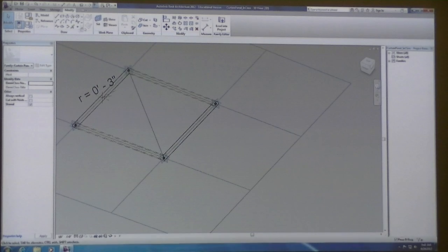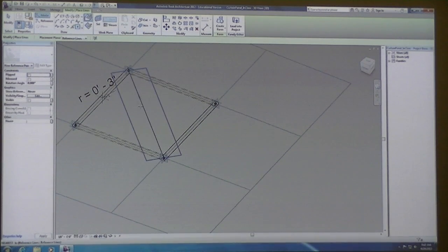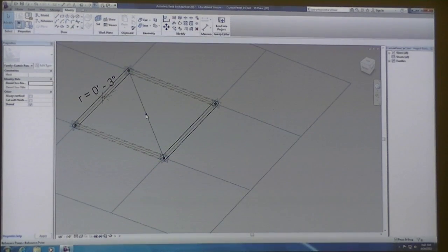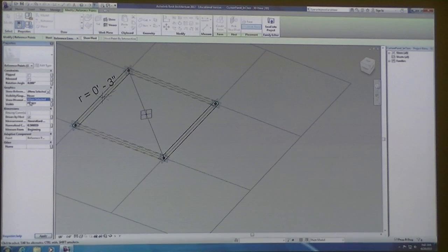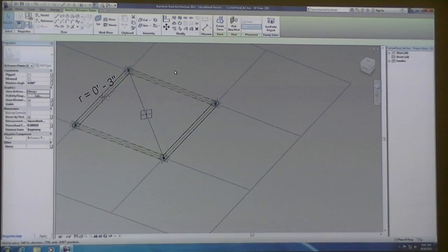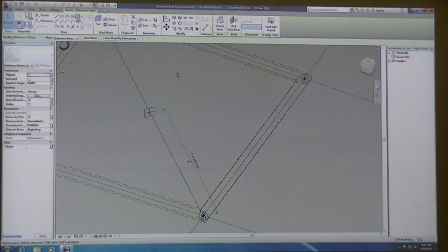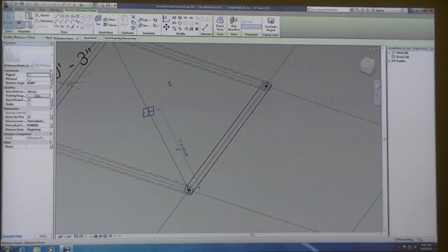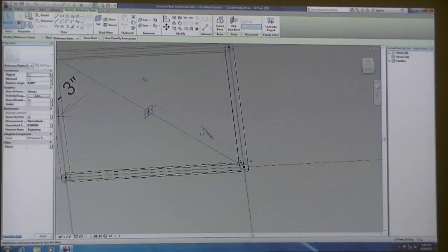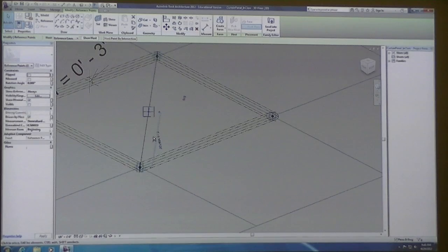And then I can, again, make a pipe. Somewhere in the middle here of this diagonal line, I'm going to put another hosted point. So you can see how these hosted points are very important to the making of basically anything in this environment. And I've turned on my reference plane. And if you're having problems snapping, sometimes you might have to rotate around the view a little bit.